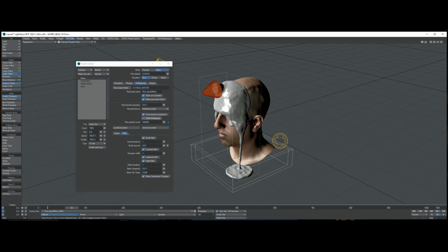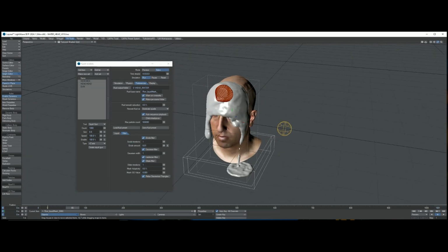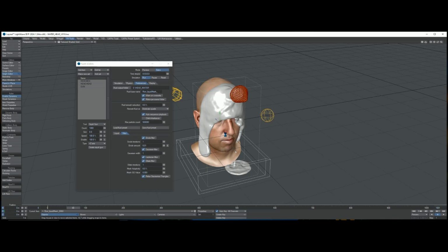It needs a while, it's a huge amount of particles, but you can see in your OpenGL preview what it looks like. And if you like it, then you can leave it, and then you have it as a sequence and can work with that. Or if you don't like it, then you stop the baking process. The baking process shows you a little more exactly what's happening as a preview. And the best is that the fluid output folder is seen by Flow CUDA, so what you do is stored directly in your scene.